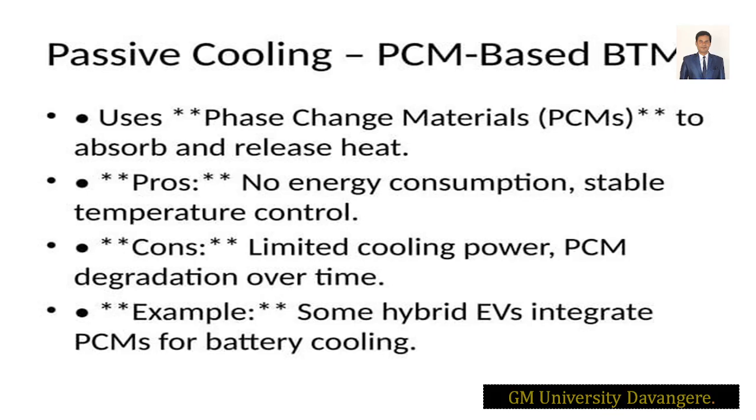It is fully based on the melting absorption of huge heat. When it absorbs heat, the latent heat, for example, for 1 kg the PCM will melt and absorb around 200 kilojoules without a temperature rise. Like ice melting at 0 degrees centigrade when you keep your cold drink. Once it fully melts, it will stop cooling until night, when it solidifies again. So this is how passive cooling occurs.